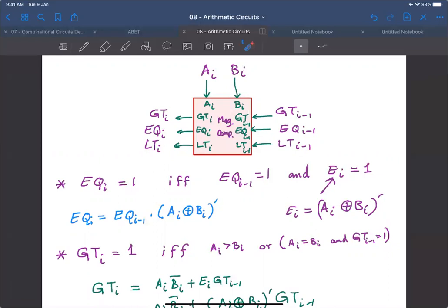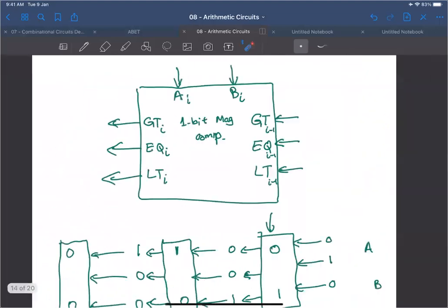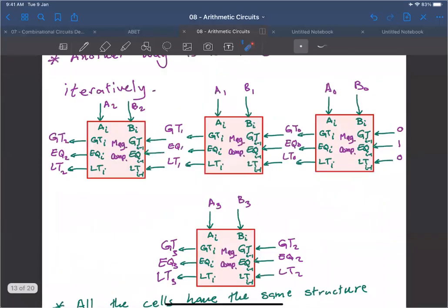However, eventually you are going to use a staged design, what we call a cascaded design. In general, the number of gates will be comparable, but the only difference is that the first approach is almost a two-level design, whereas this design is a multi-level design.